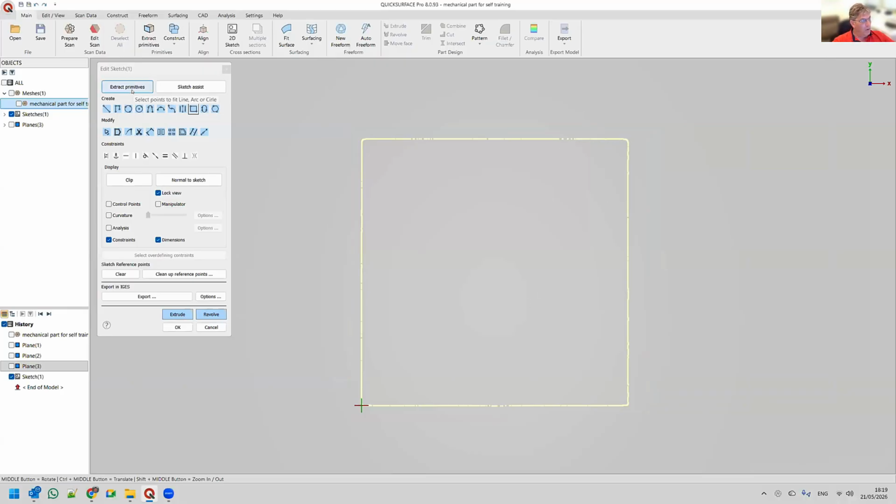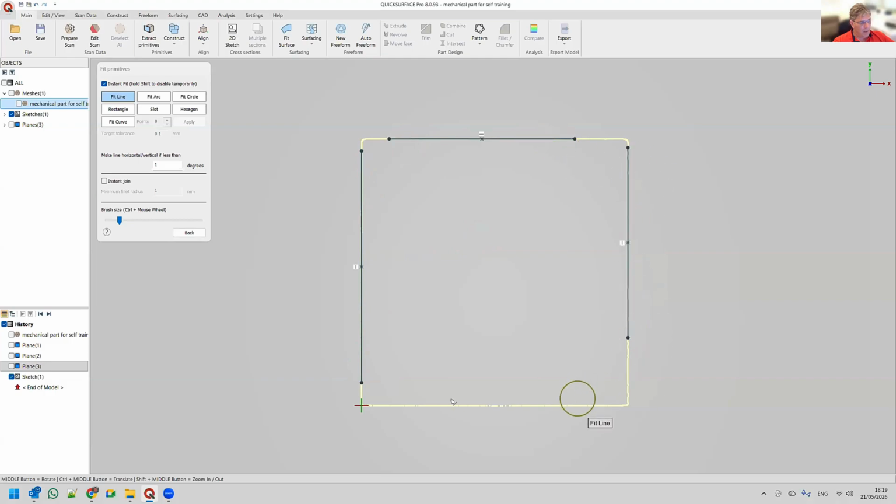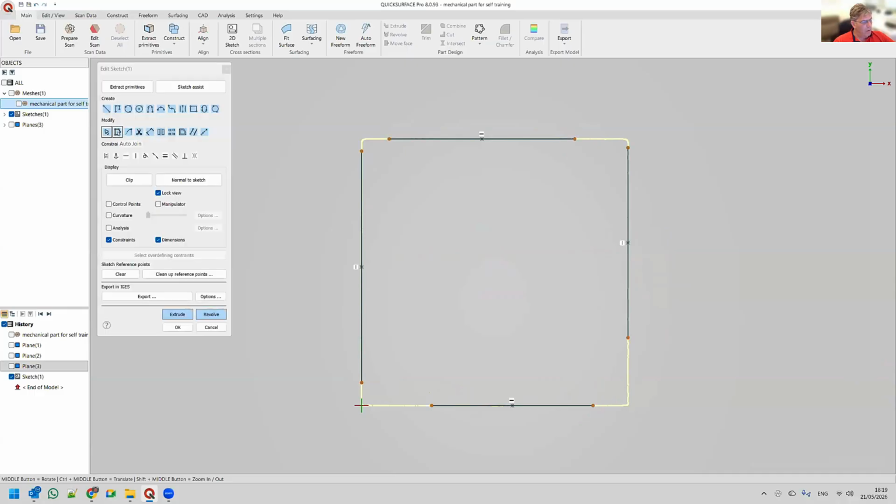We allow manual feature setting, like, okay, I'm going to just brush and say, this is my line, this is my line, this is my line. So I created these 4 lines. If you have a much more complex shape, this is really important. The software automatically will determine the best fit. And then I can just go back and say, okay, now you intersect, and it will create my first sketch.